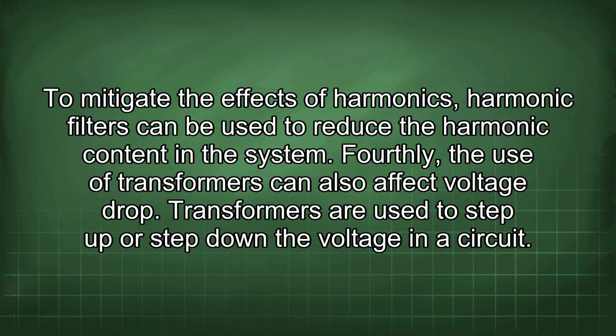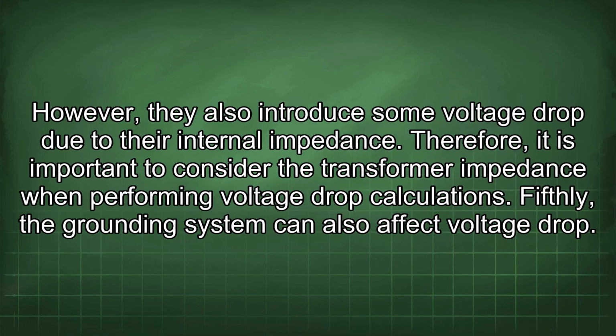Fourthly, the use of transformers can also affect voltage drop. Transformers are used to step up or step down the voltage in a circuit. However, they also introduce some voltage drop due to their internal impedance. Therefore, it is important to consider the transformer impedance when performing voltage drop calculations.